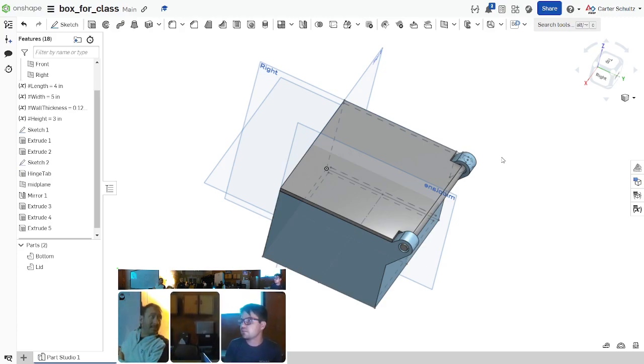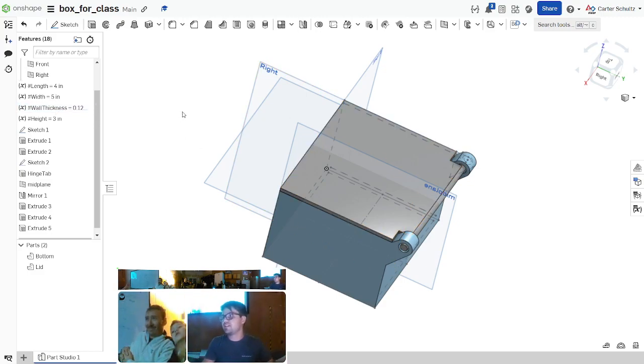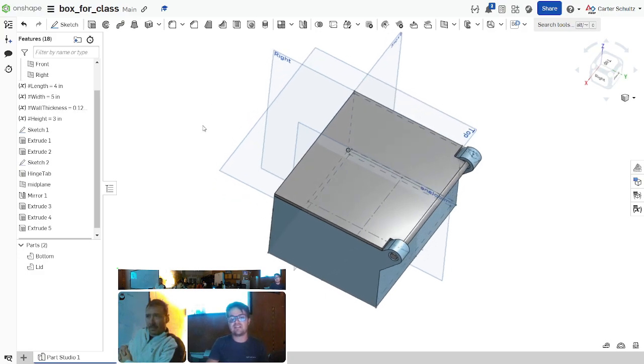No, you mentioned the tolerance. Would you add it as a new variable, something like that? Yeah, so if I go back to some of my previous designs, I will show you, I have designs with the tolerance variable in and I reuse that tolerance variable a lot. The reality is, unless you're 3D printing, in the real world, almost every part will have a different tolerance in every dimension, for reasons that are why mechanical engineers have degrees. Threads should have this much tolerance, two concentric holes should have this much tolerance, and you learn that. There's not a great lesson to it, but you could definitely make tolerances good.